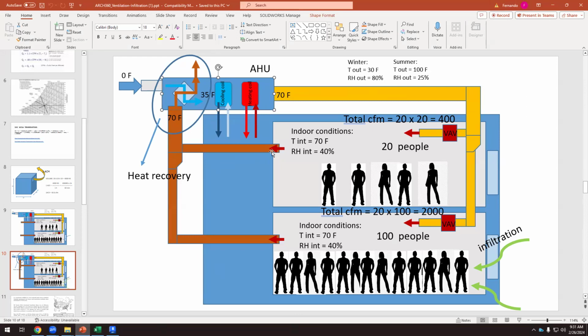But now it's mandatory that we need the return, and then we have to go back to the air handling unit. Okay, why? Because we have to make the most of this temperature that we have in this air. The air is not healthy, but it's a good temperature. It's a comfort temperature. So we need that device inside the air handling unit.